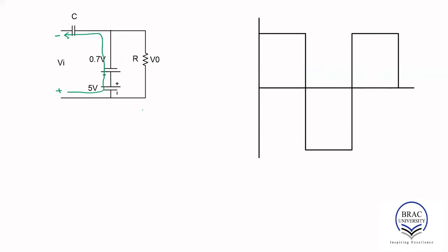The real current always flows from the positive terminal to the negative terminal through the external circuit. As the current is flowing through the diode, it is going to flow through the capacitor. As the current is flowing into the capacitor, we know that the capacitor is charging up, and it will charge up instantaneously because tau equals 0.